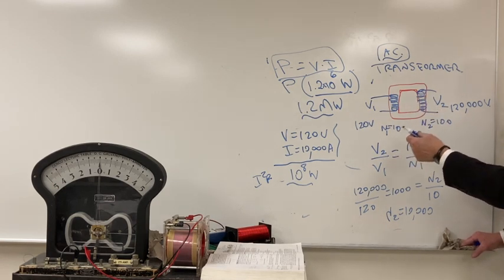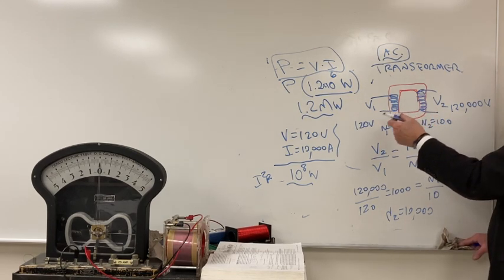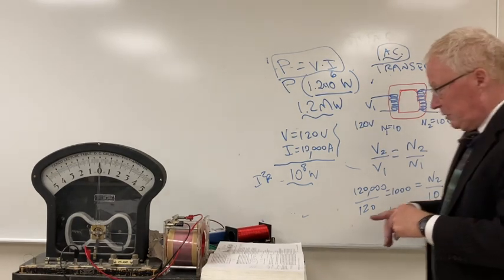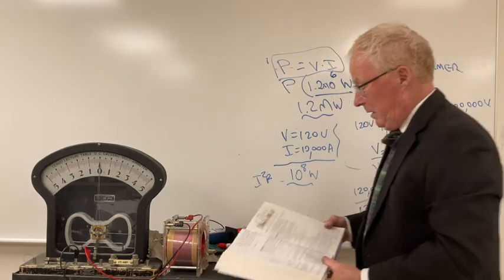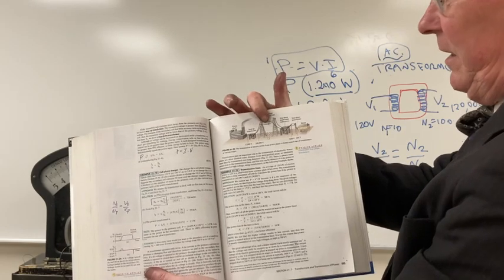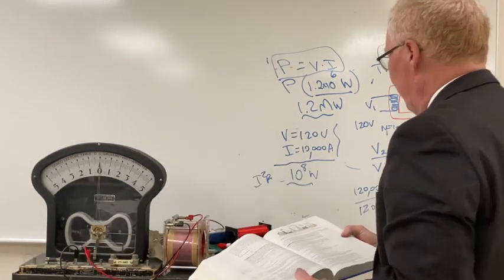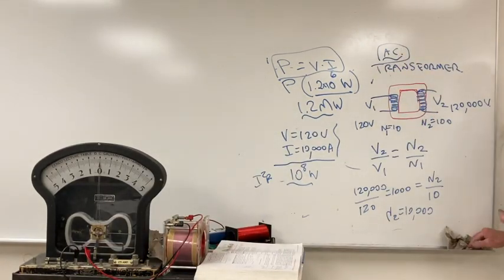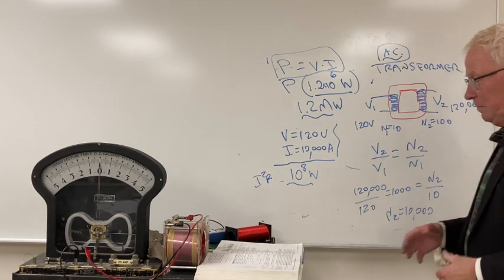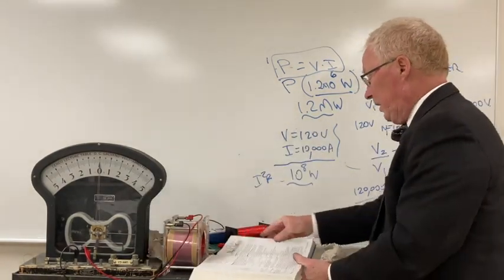Now in a real transformer, you wouldn't go quite so abrupt. You don't have that drastic a change. In a real power plant, as we're going to see, the original power is delivered very high. It gets stepped up to very high voltage and then comes down, and they do it gradually, so you don't have this huge ratio of turns. Anyway, but that's the same principle. So we do this transform. So what we do then is the power plant, we transform it up to 120,000 volts and send it down.